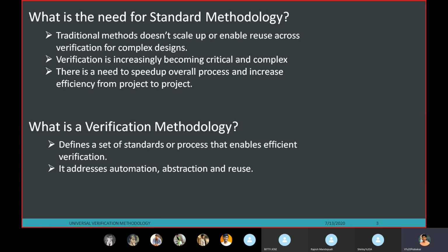So in that we will make connections between the components or TLM ports. The same way, run phase is there. In run phase, the actual process will happen. Here we are following some standards. If I want to modify anything during runtime, I will go to the run phase and modify it. If I want to create any component newly, we create it in the build phase, so I can go to the build phase and put my create method over there.